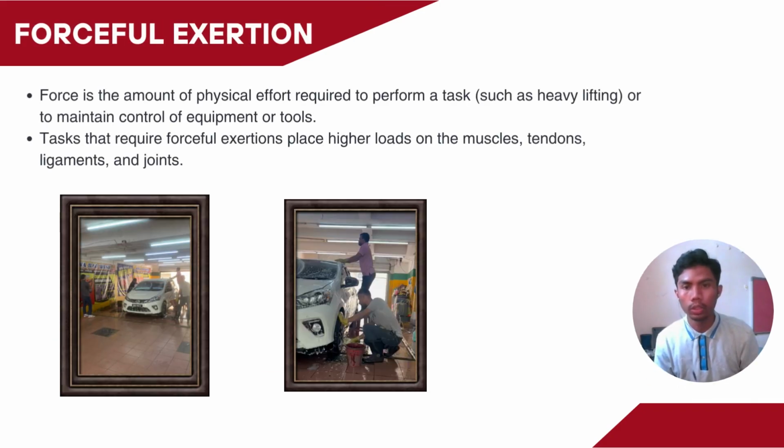Next is the forceful exertion. Force is the amount of physical effort required to perform a task. As in the picture, we know that the workers use force to wash the car, to remove the stain from the car. Tasks that require forceful exertion place higher loads on the muscles, tendons, ligaments, and joints. So the worker is only focused on their hands.